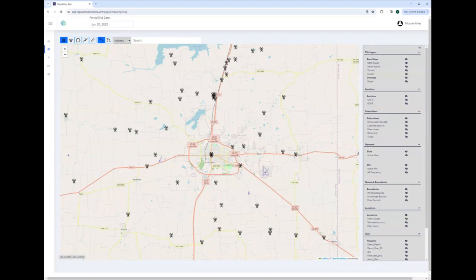Obviously, terrain and clutter is only so good. You can't take into account every scenario, especially with things like varying tree heights. But because it's pretty high resolution, we can take into account most of what's there and give you a very, very accurate picture of whether or not you can service a customer, and not only whether you can service them, but which AP is going to service them the best.